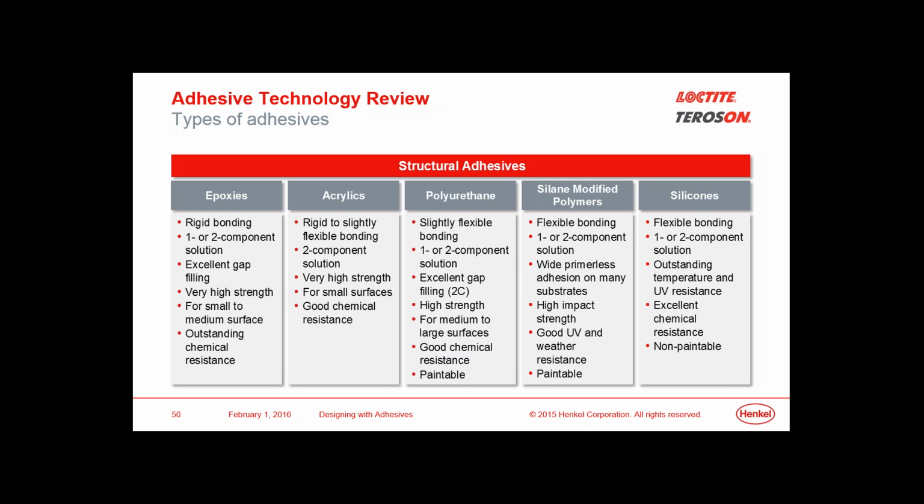Epoxies are probably one of the oldest type of adhesive technologies available. Most epoxies are very rigid with outstanding chemical resistance. Not all epoxies, of course, are very rigid, but they are characteristically stiff, high modulus, high chemical resistance, high temperature resistant materials.